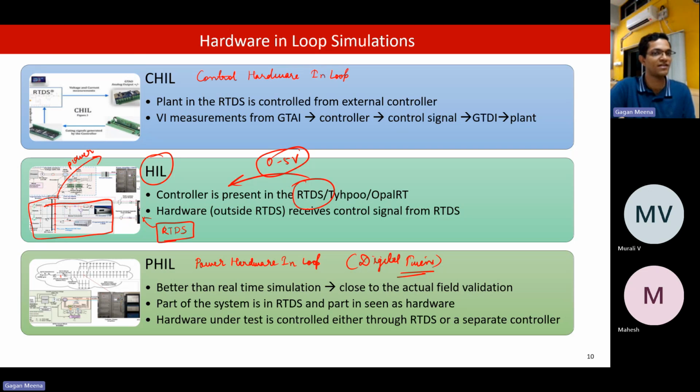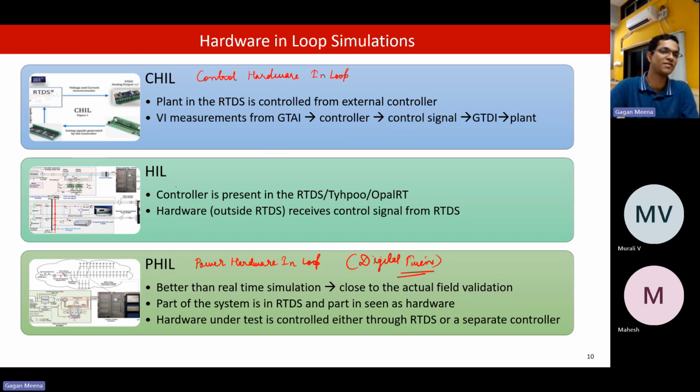For RTDS, we need to convert the signal from power to control signal, and reduce the voltage level. Or if the control signals are directly available, we can use them directly. But the voltage and current measurements are not control signals, so for that we need this.